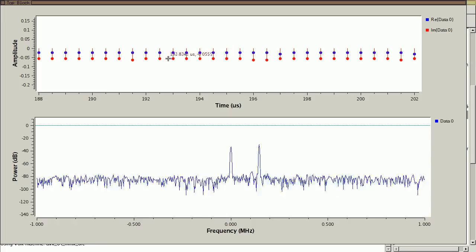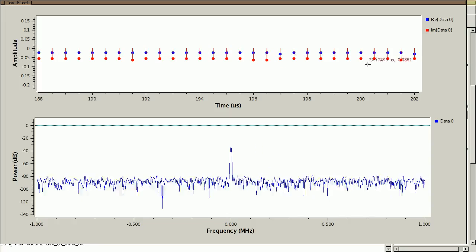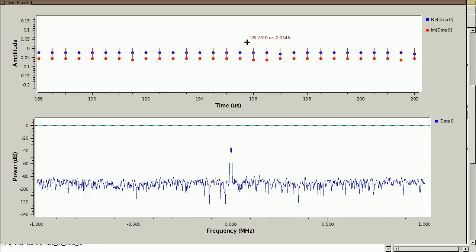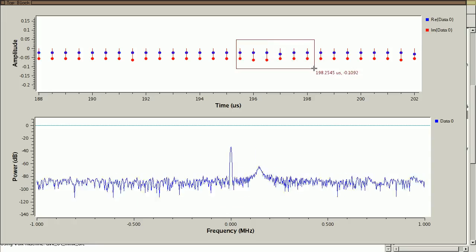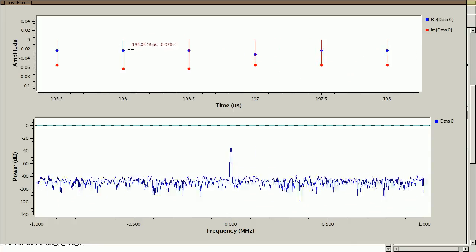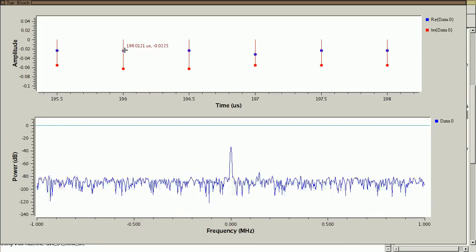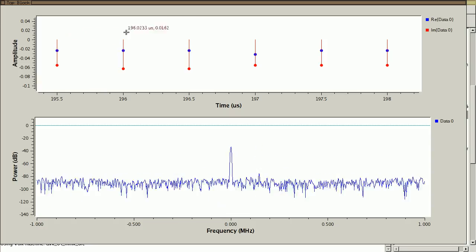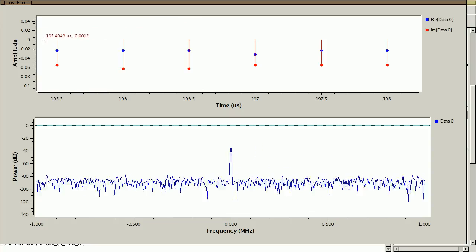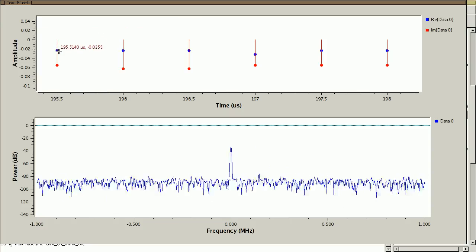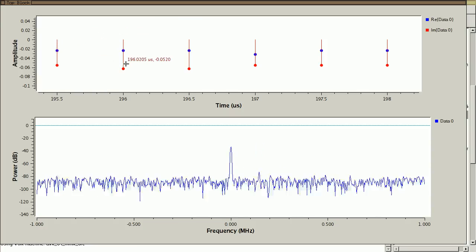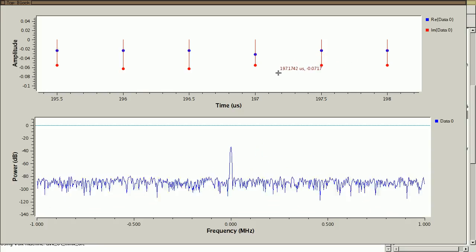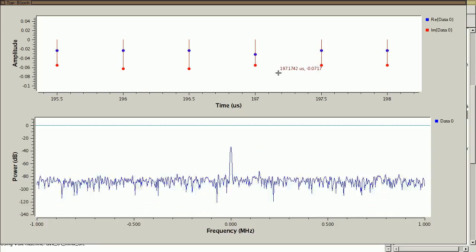And these red dots are mostly at the same value, a couple that are a little bit different. There are just a few very distinct values that have samples assigned to them. So you can actually see, and if we were to scale these up by 256, you would see that these are integers. So for example, this might be 0, and this might be a negative 1, and then this dot would be at negative 2, and so forth, something like that. What we're seeing is that very little of our dynamic range is being used.